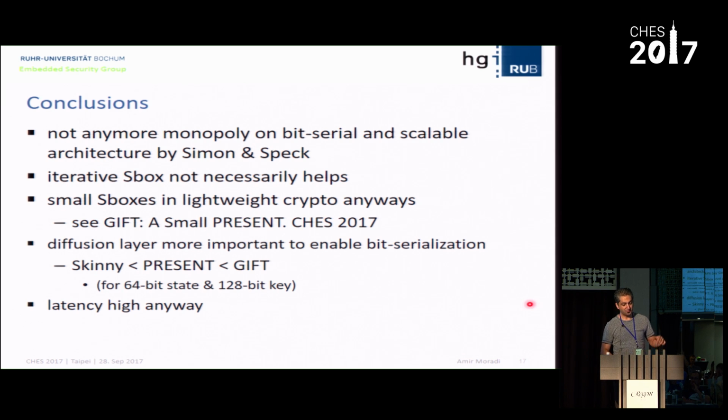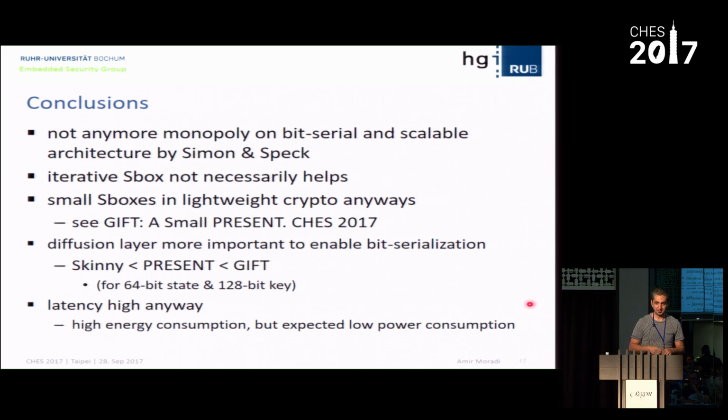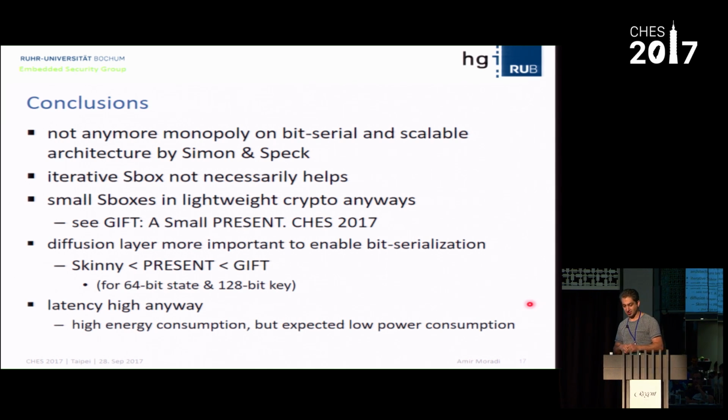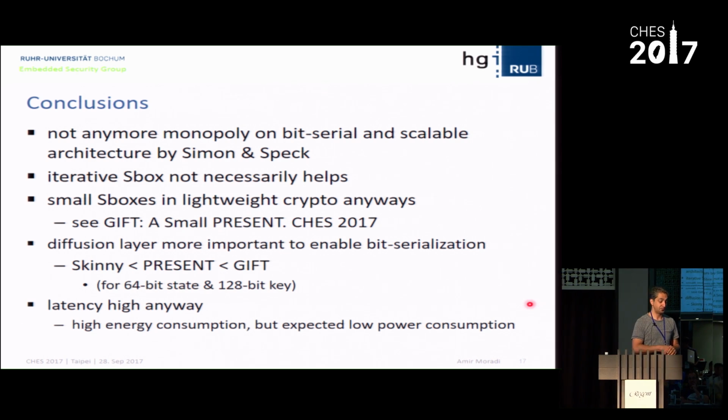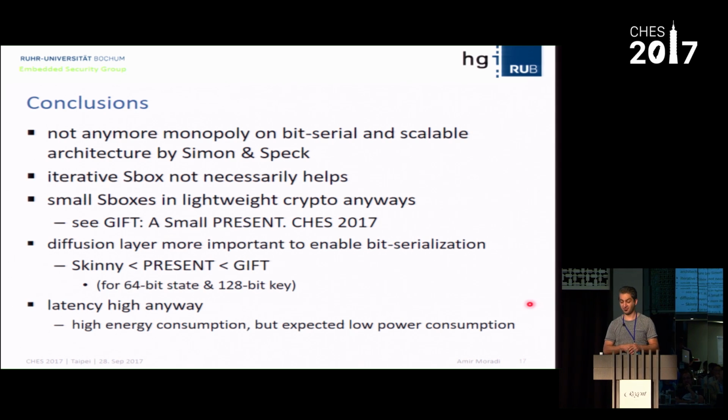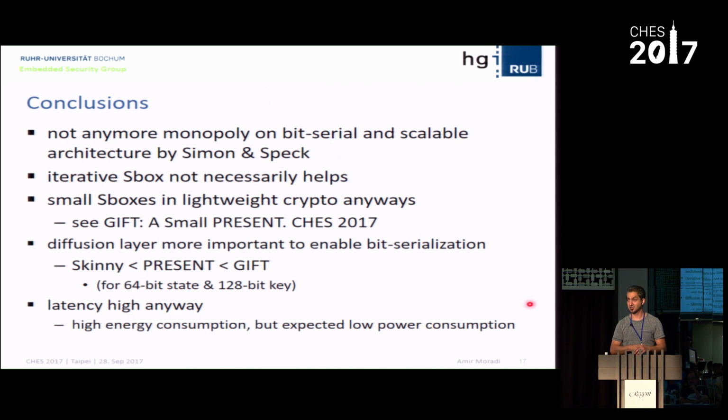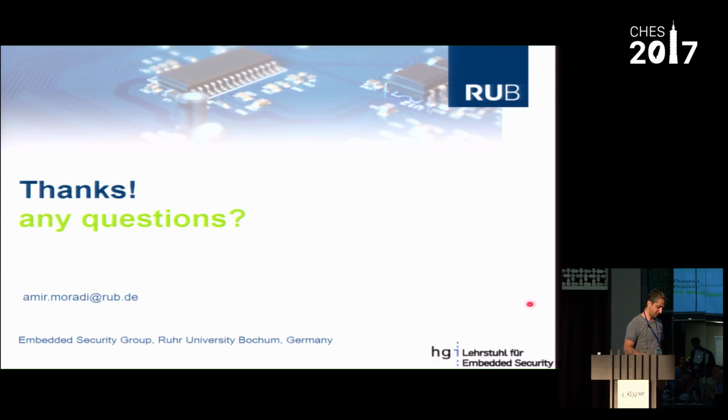Of course, we have very high latency in this bit serial architecture, and we know that it increases the energy pretty much. I mean, it's definitely not suitable for low energy applications, but we expect low power consumption, particularly for RFID passive tags. If the amount of power consumption is limited, it might be helpful. Thank you for your attention.